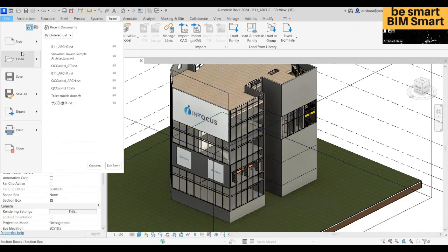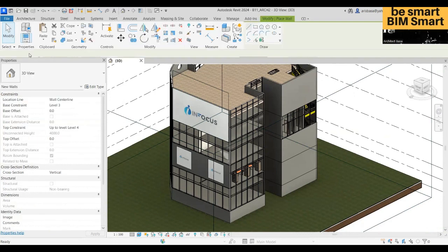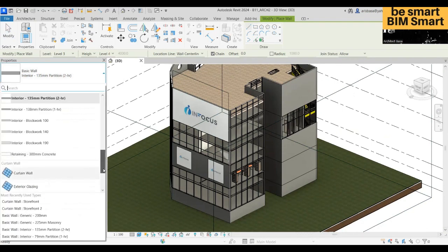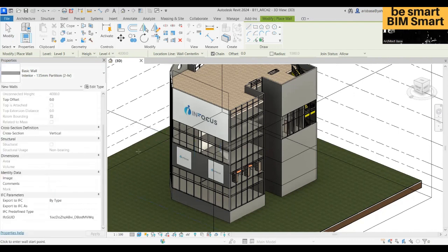When you start a wall, under architecture, you have here wall. You have what you call here as curtain wall right away. Because what we did is storefront. Storefront is something that is already having the mullions. Now, curtain wall is something else. We'll do that later on. Okay. Why don't we do it now? Why do we have to wait later on? Okay, let's do it now.